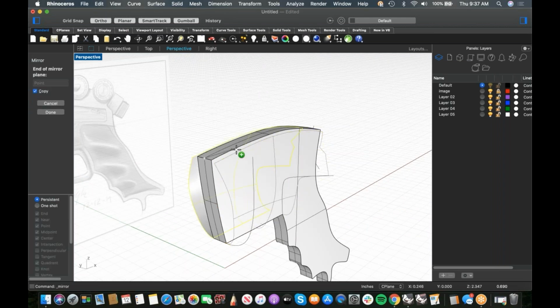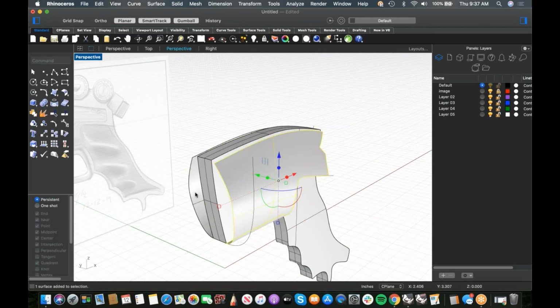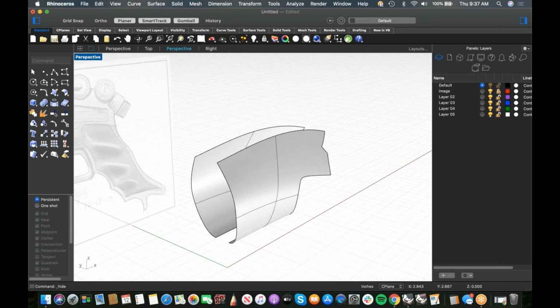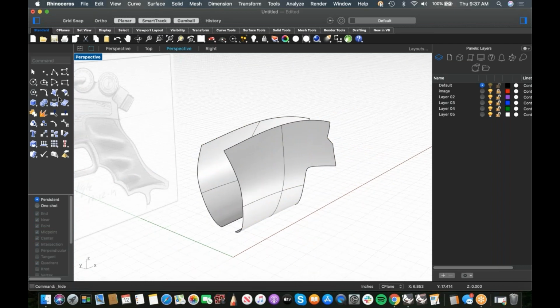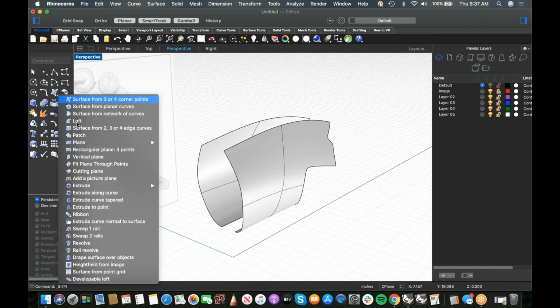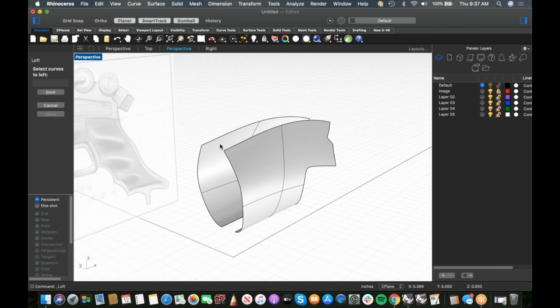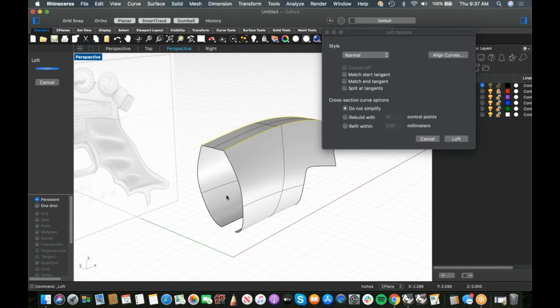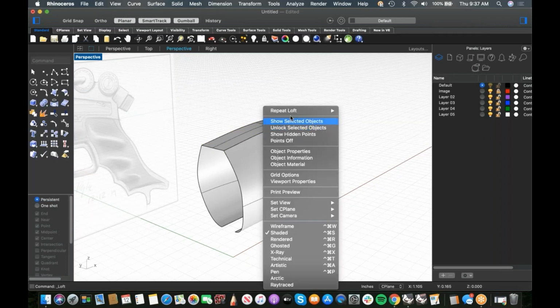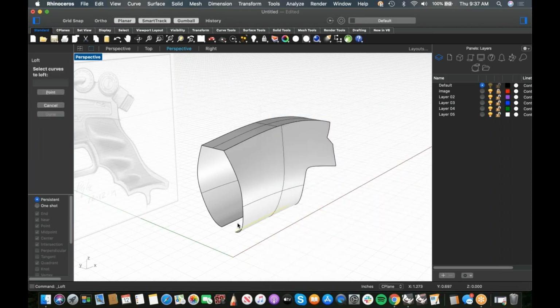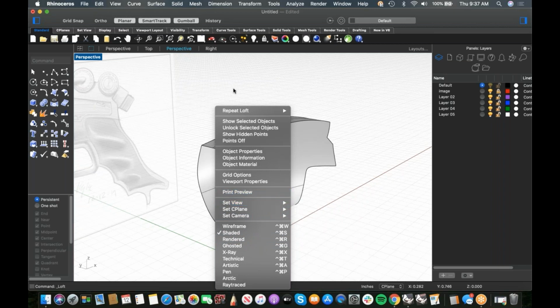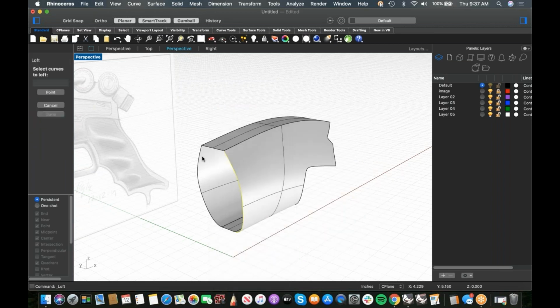And then what I'm going to do, I like to build, I refer to them as chunks. I like to build in watertight chunks. And so what I'm going to do is attach these two guys and make them into a chunk. And that way I know that it is going to be watertight. And at the end, when I've finished the model, I can basically just really quickly go through and Boolean stuff together. And it's easy to deal with.